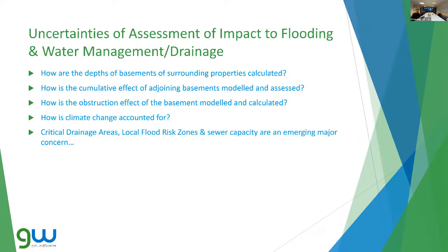Each of these different areas has different characteristics. You could have one in Camden where there's very shallow London clay, and therefore you could get rising groundwater or perched water on top of the London clay, just because it cannot drain anywhere. That could lead to groundwater flooding and obviously surface water flooding.